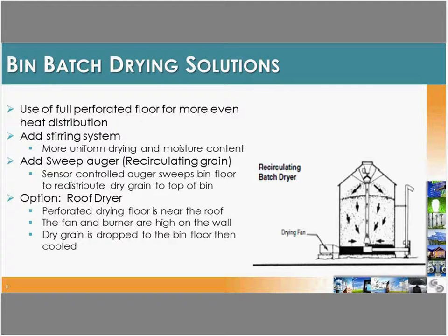Moving into this next slide, we talk about bin batch drying solutions. Utilization of a full perforated floor, so the whole bottom floor is perforated to get even heat distribution going up through the grain. Adding that stirring system,